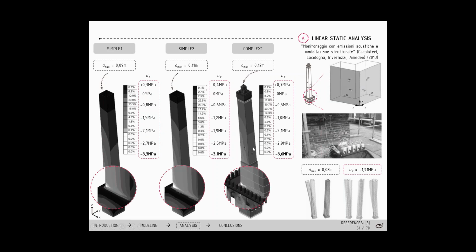The most stressed part is concentrated in a very limited area at the base of the tower, below the direction of the greater inclination, meaning southwest, and a situation shown also by the percentage of elements under this stress, which is a little lower than 0.1%, as you can see here. In this exact position, the acoustic emissions monitoring was developed, meaning the models represent a real distribution of stresses.